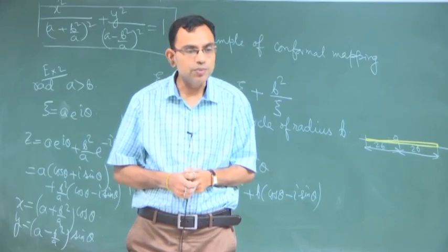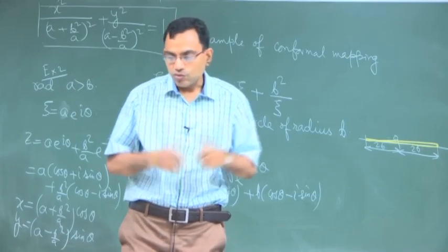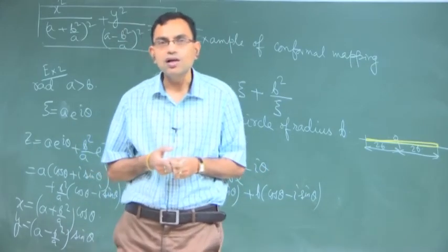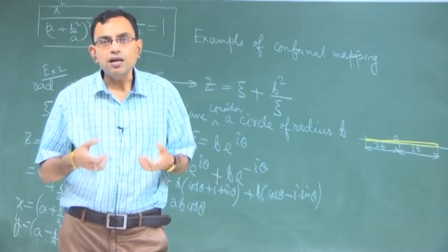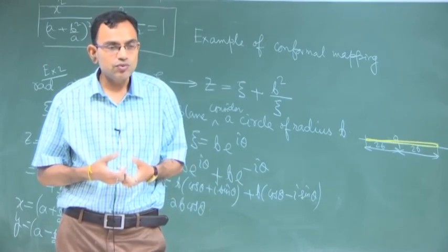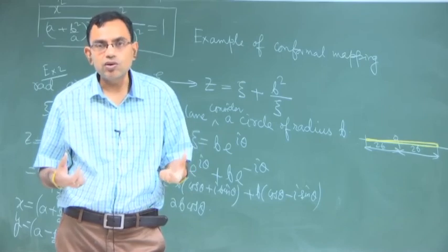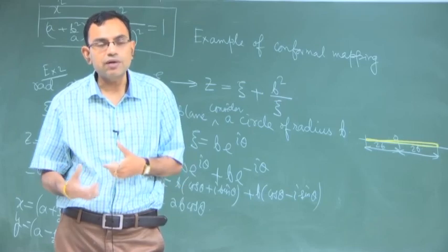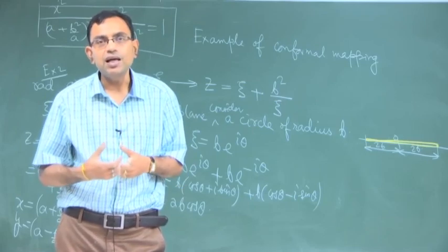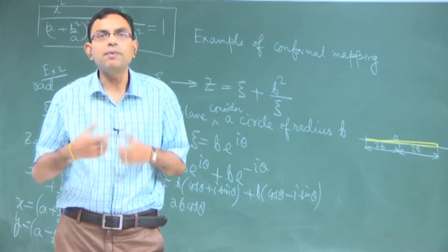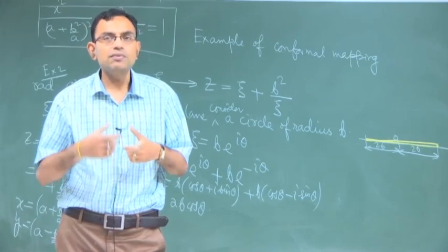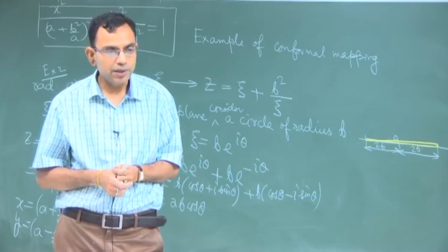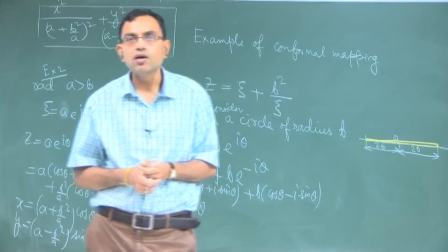more complex geometries. To summarize, we have discussed various aspects of potential flow, starting from simple elementary flows. We have constructed flow past a circular cylinder. With rotation we have seen how to calculate the lift and the drag force, and then finally how to generate bodies of more complex shapes from the consideration of a circular cylinder or a circle in one particular plane by using conformal mapping.